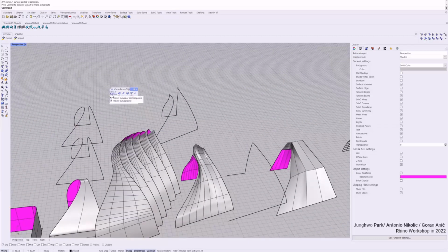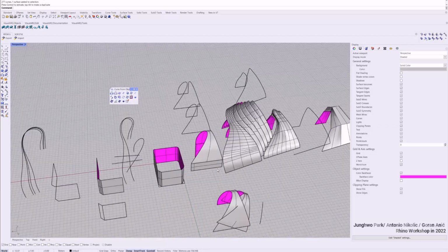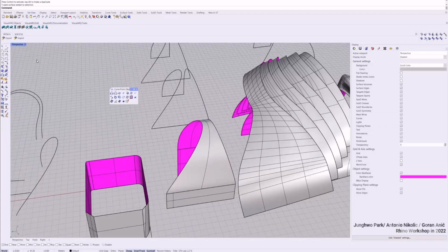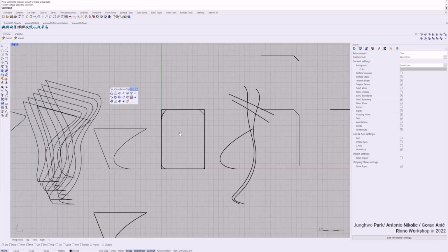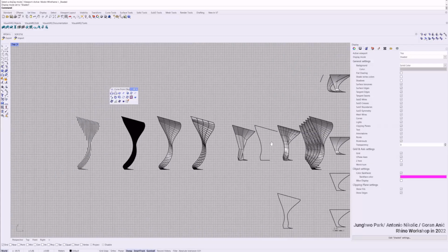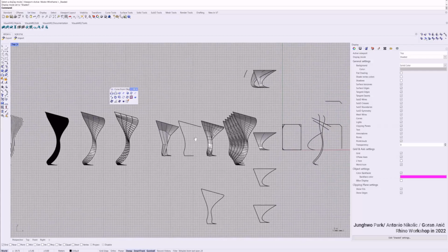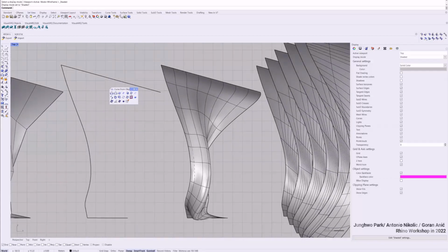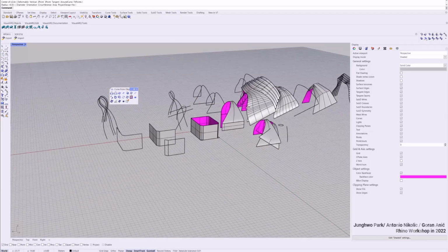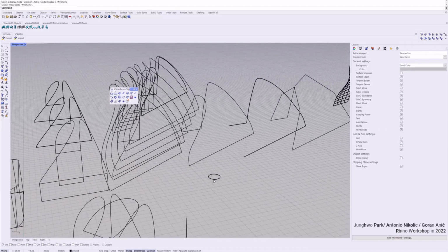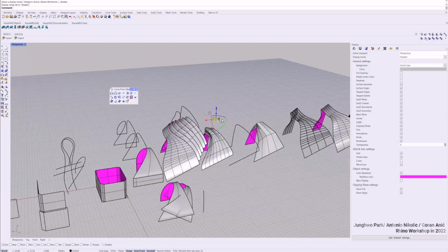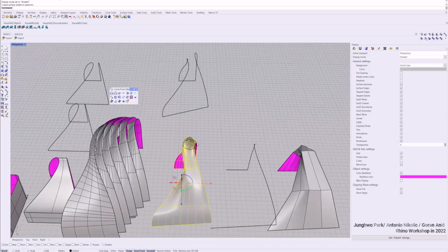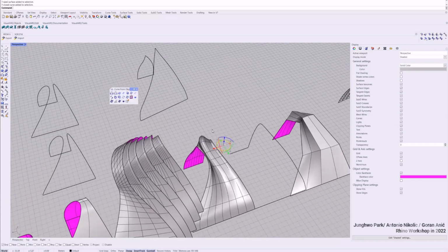There are so many useful tools, or yeah, maybe projection could also be interesting. Let's say we have this surface. I'm gonna draw from the top view. This is the most complex surface, so I'm gonna draw one circle from the top, and let's bring this circle up. I was in the wireframe view, shaded view, and now I'm gonna project this one circle.